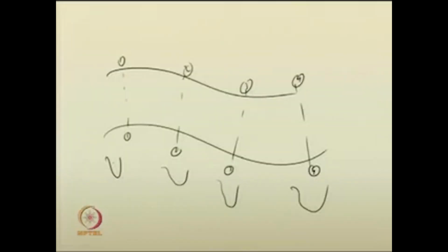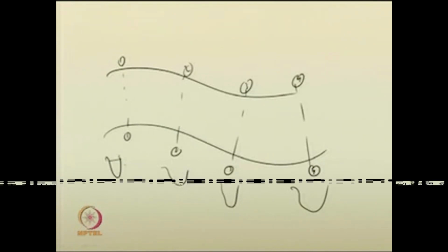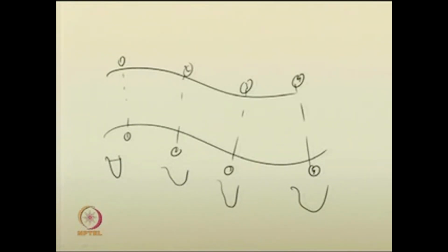Once you record all those things, you know the distinct site locations of the channel reach. Between two stations, you can average the properties. Suppose all the properties are given here. Now, if you want to evaluate the flow depth at this location and this location, you can use the standard step method. That is also a varied flow property, that is gradually varied flow. Using the standard step method, you can evaluate the depth of flow.